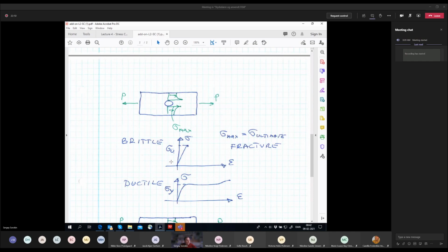the value of the ultimate stress, you remember, I hope you remember this diagram. I think you had it with Joran Kepler. This is the uniaxial loading, then you have this epsilon, and here you have stress, and this is brittle material. So you have a linear performance, and then you attain this point, and that's it. You have the brittle failure of the material. So this is the ultimate strength.